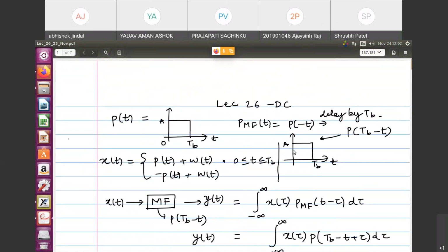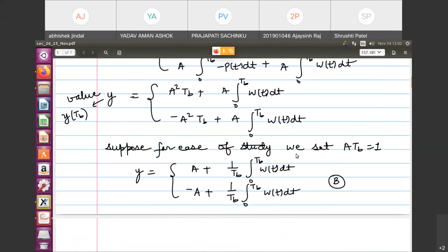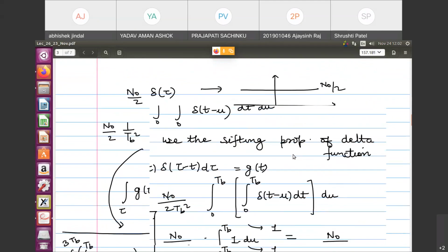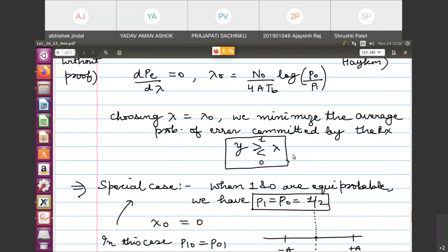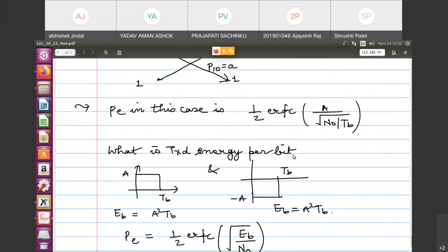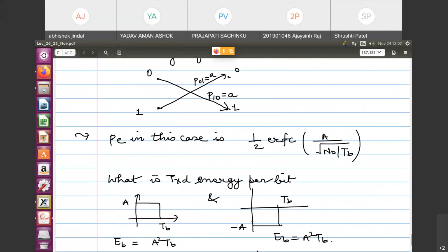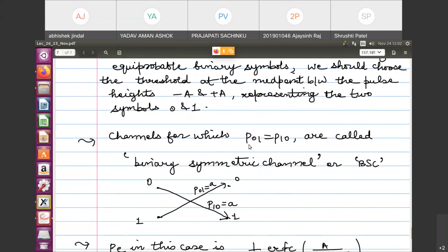So we are basically undergoing the detection or decision theory, which is employed in digital communication in order to retrieve the information sent by the source. Last time we discussed the error rate due to noise, and we finished this whole derivation. We said that this is a binary symmetric channel if P of 0,1 is equal to P of 1,0. This is the condition for it.